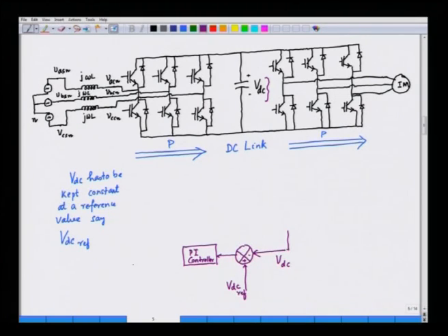So, in this case we will have a limiter here to limit the value of the current, we can have a limiter in this case, and what we obtain is the reference current amplitude ISM, and that is converted to the reference current by a reference generator into the three references, and the references are ISA, ISB and ISC.